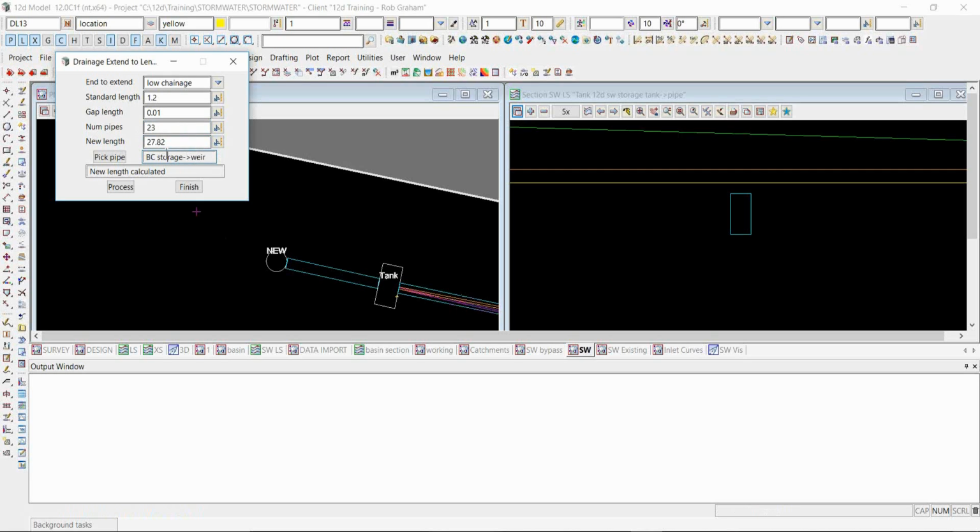And you might be wondering, well, why aren't I going to 24? These tanks, they're 1 meter long, so I'm getting 2 square meters out of this tank. And when I've got another tank at the upstream end, I'm getting 2 square meters there. So I want to make sure that I do not double count the storage. That's why I'm going to just my 28 rather than 30.